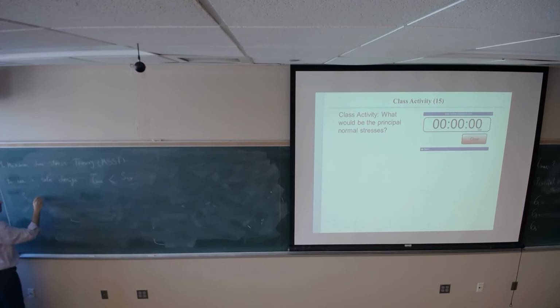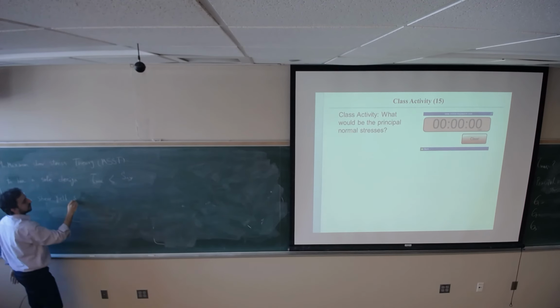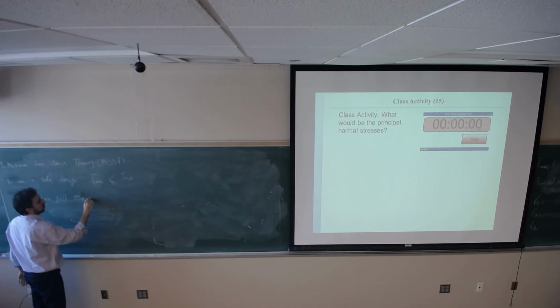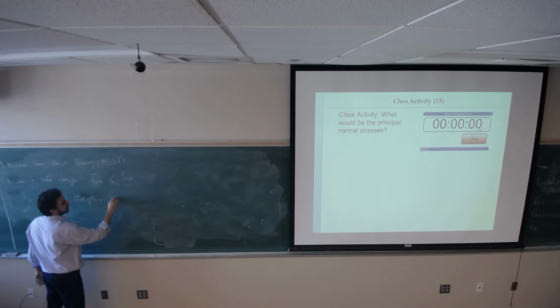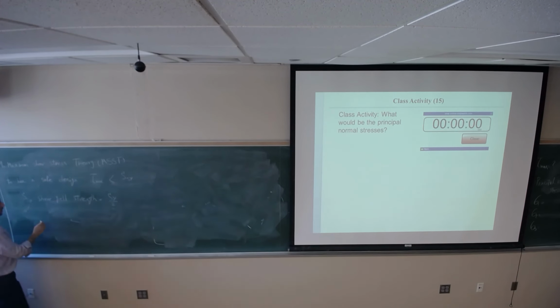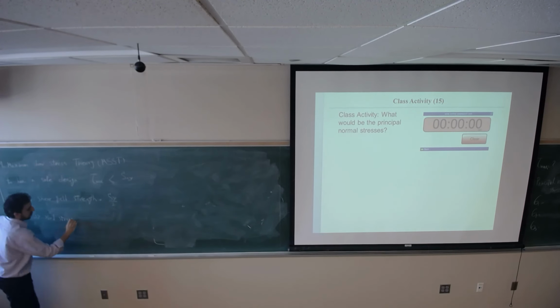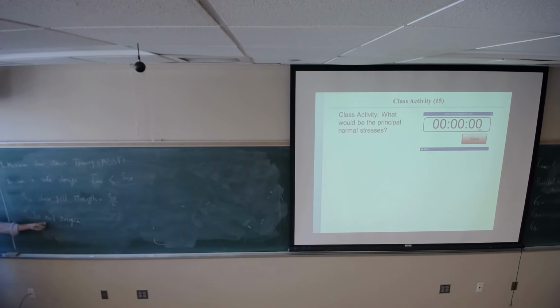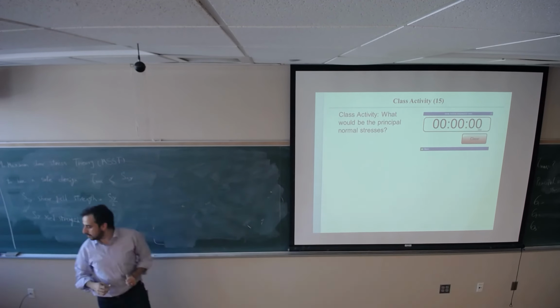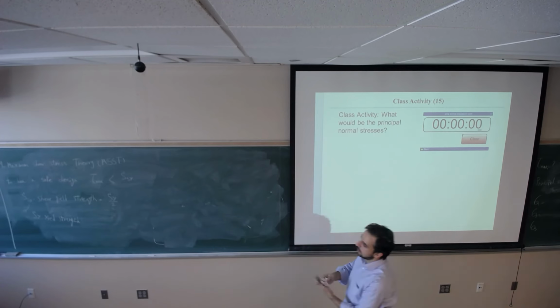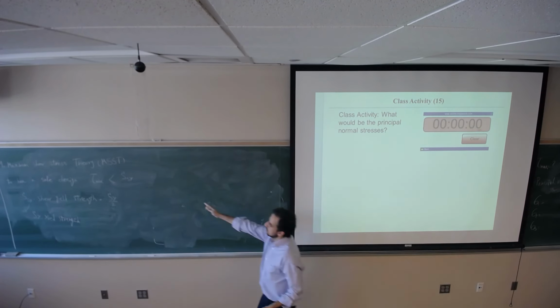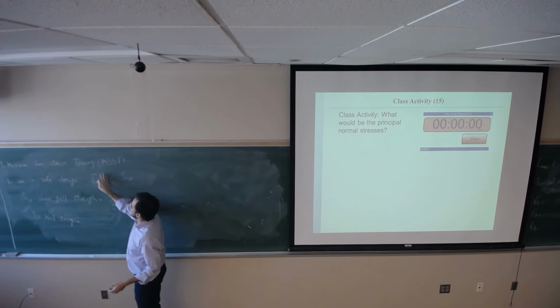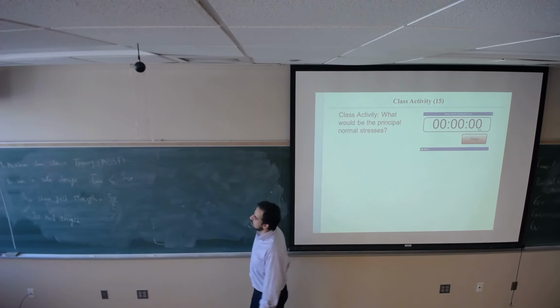So shear yield strength is equal to SY divided by 2. And SY is the yield strength. It's coming from the table, depending on the properties of the material. If you divide it by half, you can find this side. As long as tau max is less than SSY, we have a safe design.